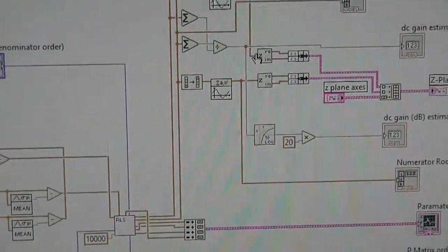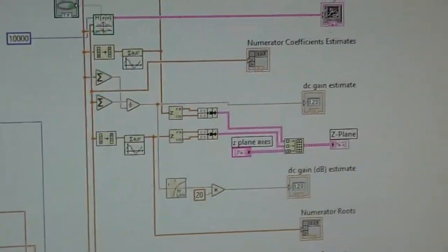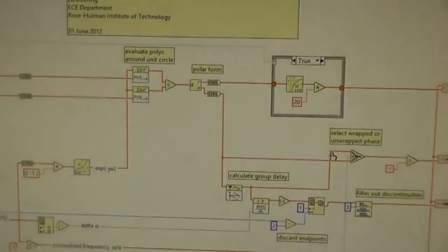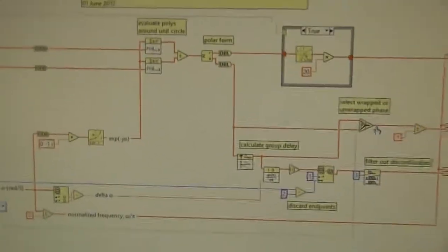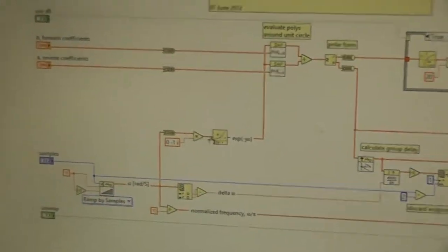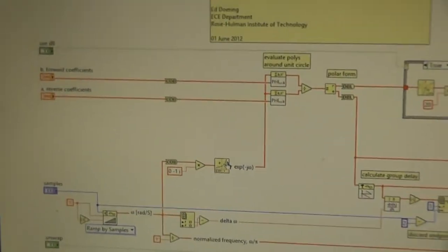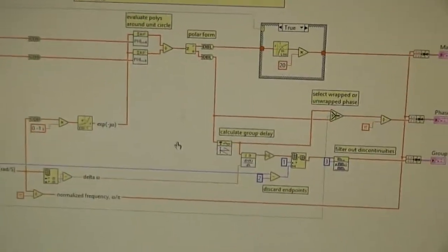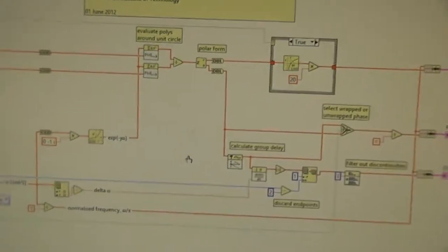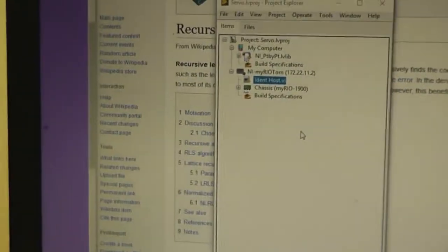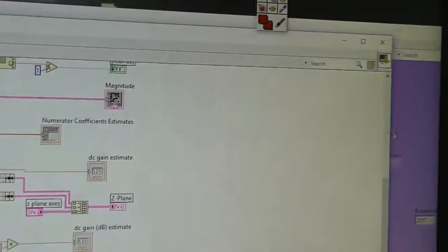And this is using this. So I'm using this little routine here, to give some credit to this guy Mark Yoder, who wrote this nice little Bode-plot thing which scans through the frequencies. So given a Z-transform model, what this does is it plots the analog Bode-plot. We don't really need the phase because it's going to be non-minimum phase, so we can deduce the phase from the magnitude anyway, so that's not really of importance.